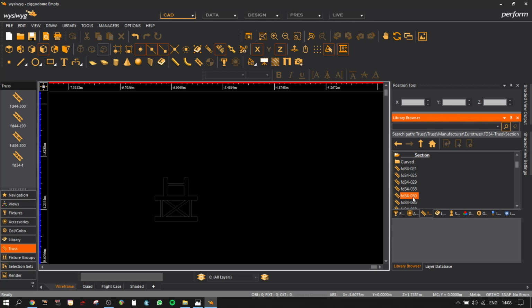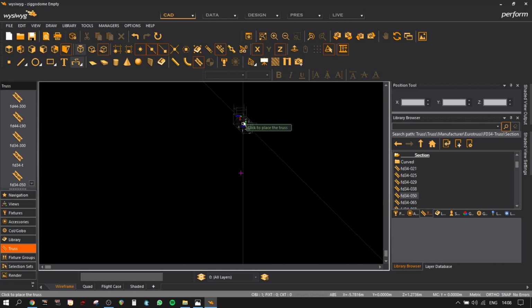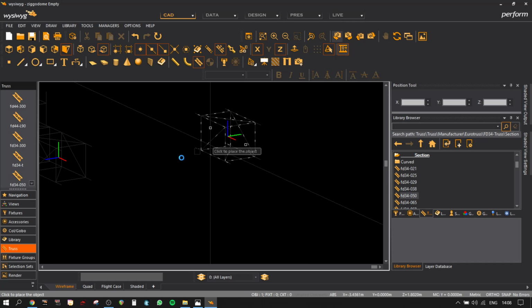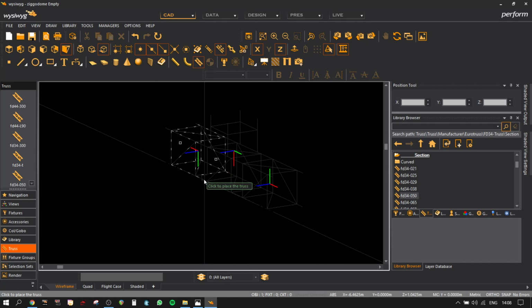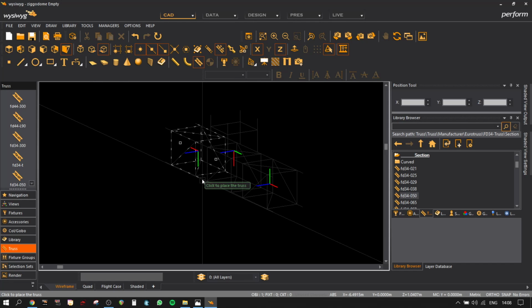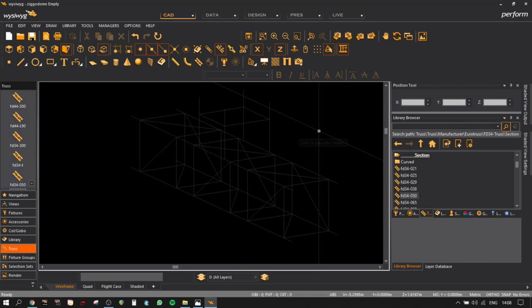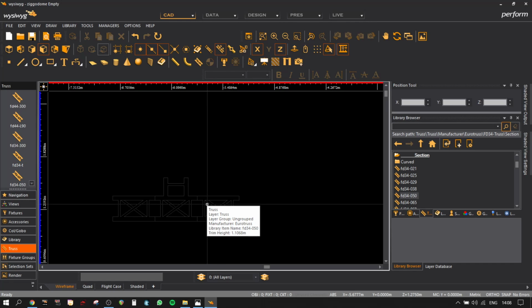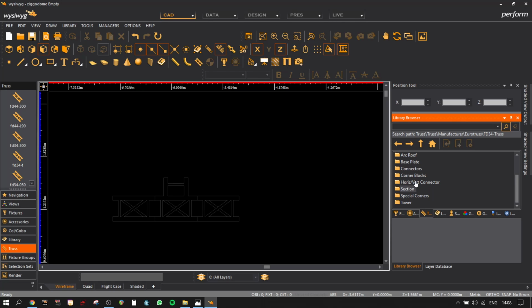And the next shortcut we're going to need, most of the time I try to build my trussing in the, how's it called, isometric view. That way I can see exactly where it's snapping to, because sometimes if you use a front view it will snap to the back pipe of the truss, and that's not really what I need or what I want.